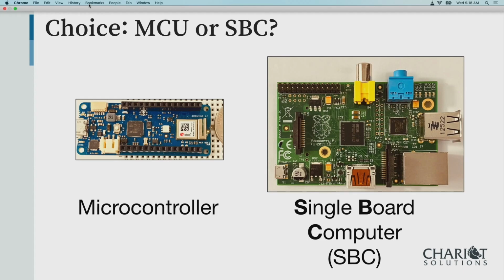Your main inflection point in terms of the physical devices is whether you choose a microcontroller-based device or something that's like a single board computer. And again, for video encoding, you probably need a single board computer, because they're always scaling up the performance of these microcontrollers and what they can do. But let's just assume for now that that's an inflection point, that you either have to have an operating system, multitasking, programming in a higher language, like maybe you want to program it in Python, or JavaScript or Java or something like that. A little bit of a stretch depending. But single board computers can do that.